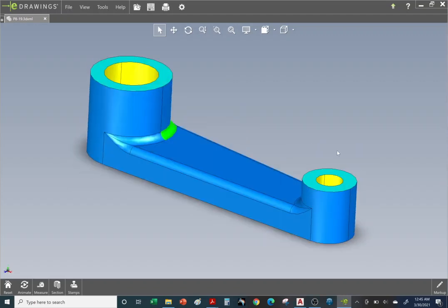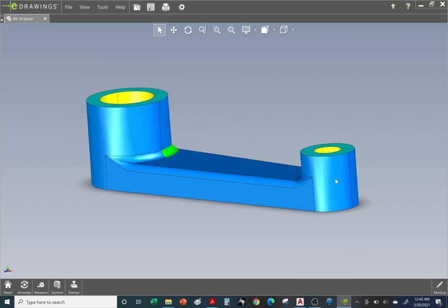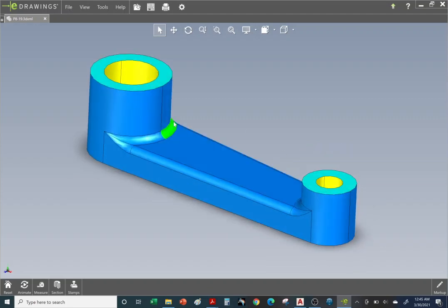One thing about this part is that a part like this is actually poured into a mold. So this would be liquid metal, and let's say it's aluminum, and it's poured into a mold. And once it goes from a liquid to a solid, all this has a rough surface, so everything will have a rough texture to it.